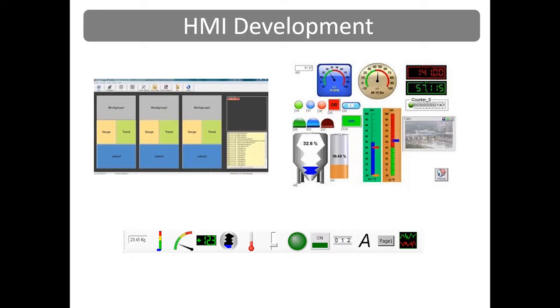Easy Data Logger allows you to make different layouts and has a variety of gauges, numerical displays, and other objects to choose from so you can display and present your information. You can also import your own graphics. It has work groups, gauges, trend reporting, and allows you to visualize the information. Later in the training, Robert's going to be showing you how to develop an HMI with Easy Data Logger. And also is going to show you the data logging of information from data acquisition modules.